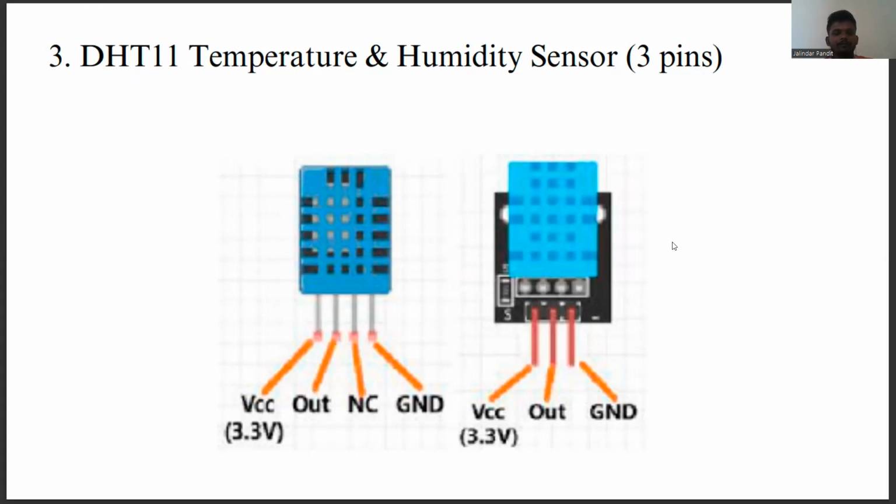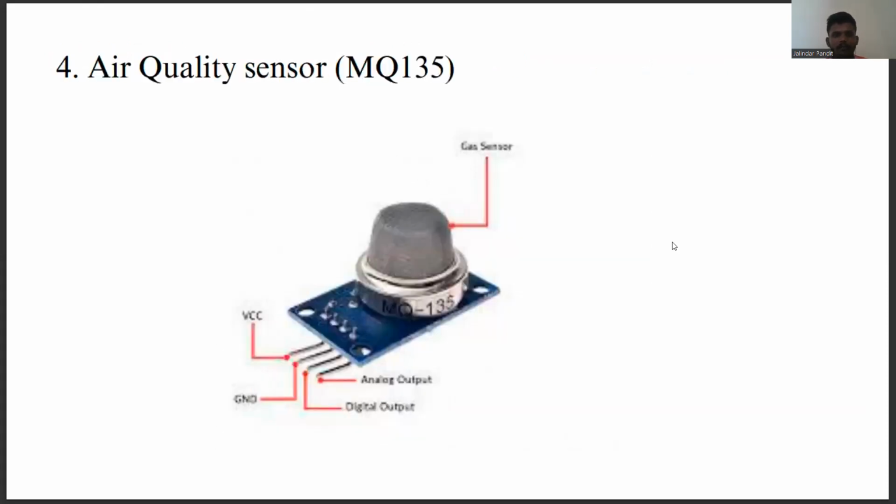So the DHT sensor involves measuring the resistance of the thermistor and the humidity sensor. Then the sensor converts the readings into a digital signal which is sent to the microcontroller board, and through the data pin the microcontroller board can interpret the data and display the temperature and humidity reading on a display such as the 0.96 I2C OLED display.